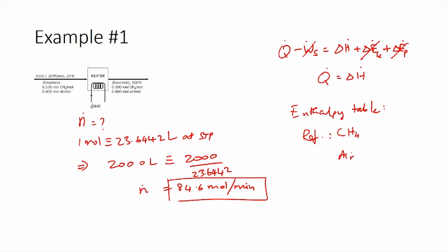Identifying appropriate reference states is crucial for performing calculations in a simpler fashion. As I had already mentioned, combustion gases such as air, oxygen, carbon dioxide, carbon monoxide, which are involved in combustion reactions, commonly have a table where you can get enthalpy data from. So, using the reference state from the table would be appropriate for air.